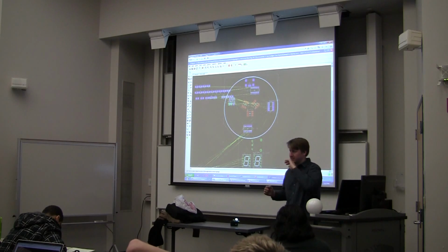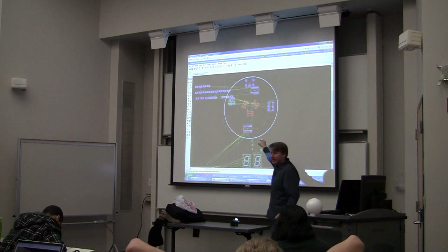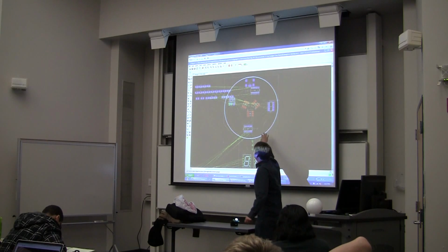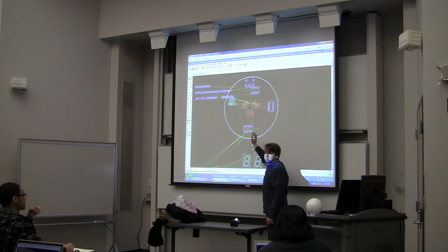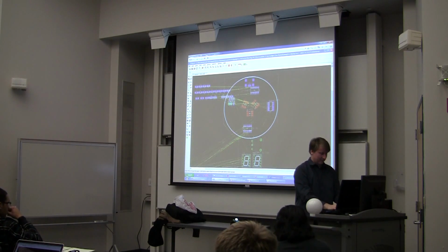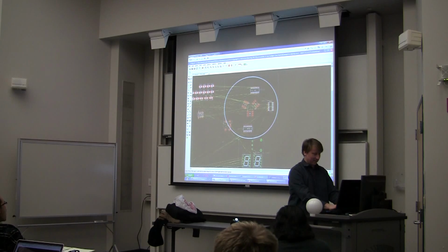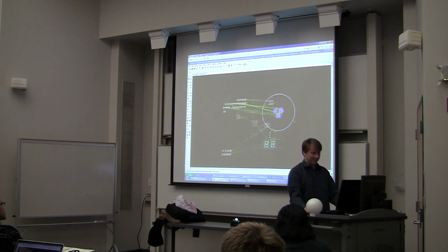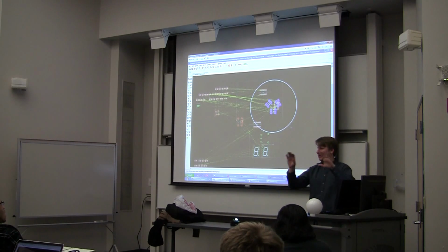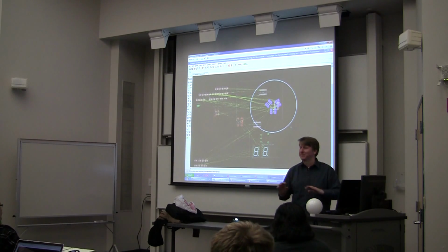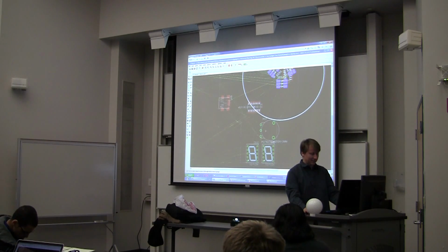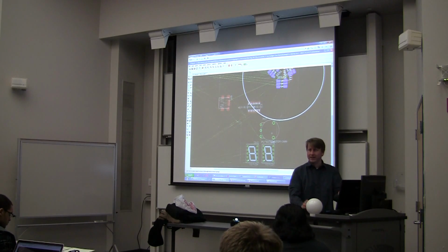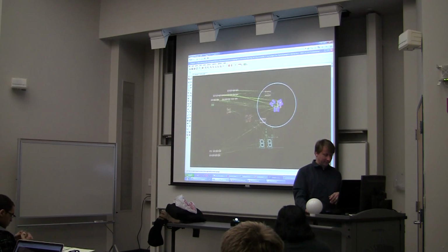However, for your gadgets, what we're going to ask you is, right now my complicated side is the bottom. It makes our life much easier when you make sure your complicated side is the top of the board. So if you want to do something funny like this, what we ask is you do it the other way, where you say, well, now in my head, I know the bottom of the board is the top, but the top is my component side. That's where all my parts are going to go. And then you need to make sure you mirror your displays. The potentiometer stays on the bottom of the board, then I leave it as is, or I can mirror it.